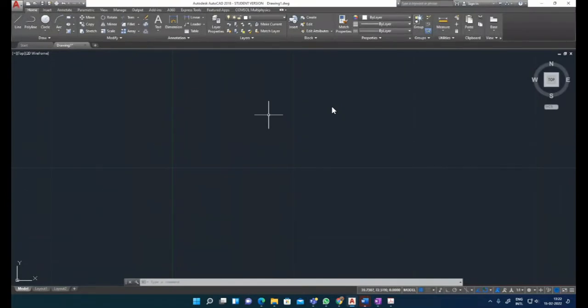Okay, now we can see the same thing in AutoCAD. I think we already set the limits. Now we can start with the line command. Line. Now see, it's asking to specify the first point. You can take any point. The limit was 100 and 0, so we can take 50, 0. That is the first point. Now see where it came, somewhere here. Now you have to write down the next.